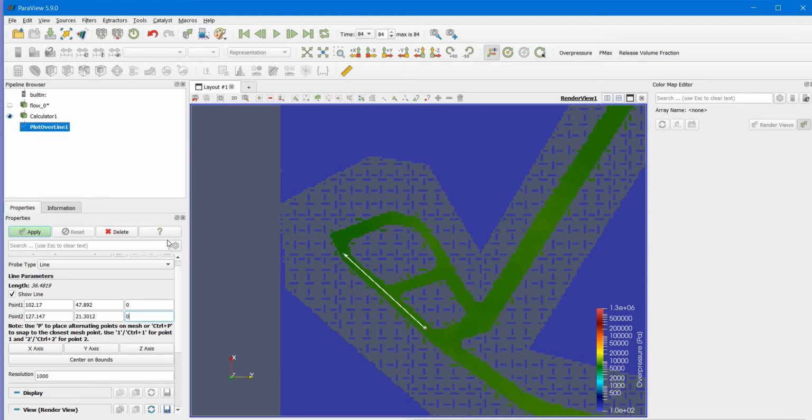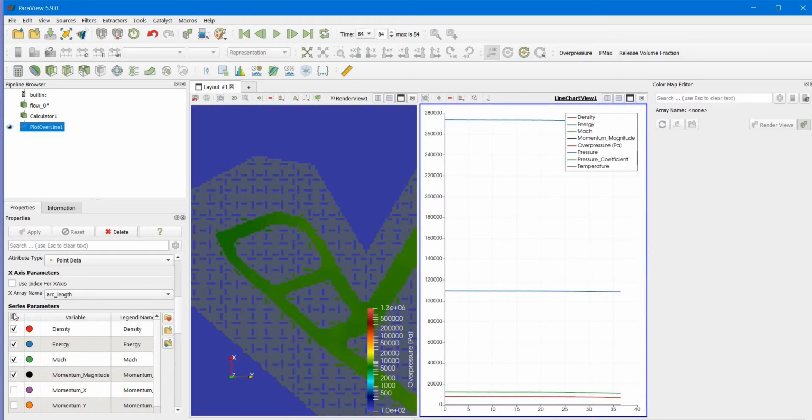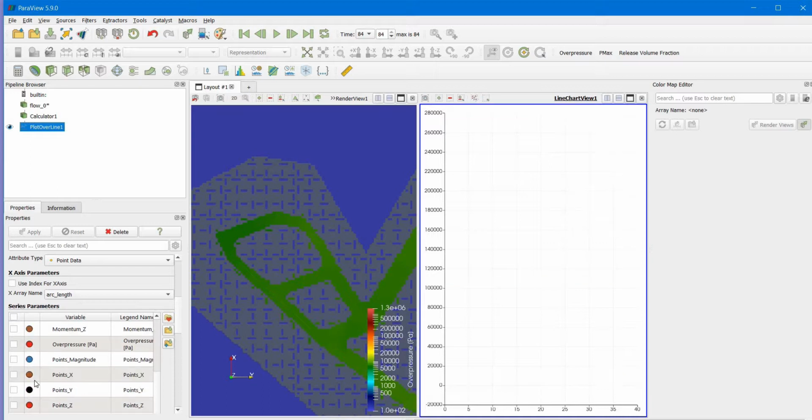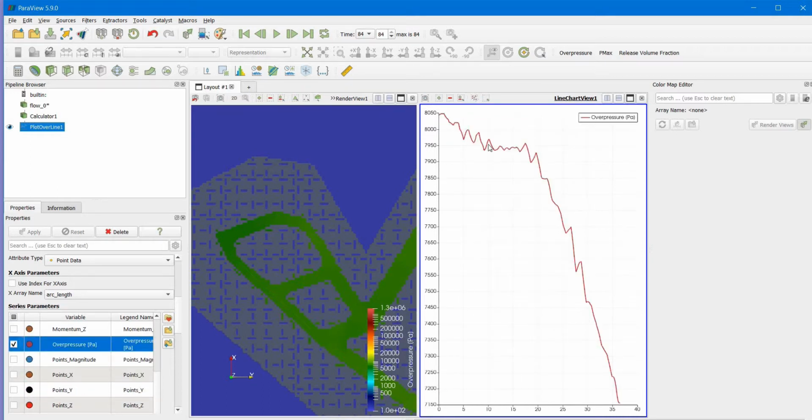And so if I apply, all I'm looking for, I don't care about the other stuff now, is the overpressure. So I've got 8,000 pascals, so that's under 0.1 bar. That in itself won't kill anyone. So unless there's structural damage here, which this maybe can cause, I think people would survive. But let's see if this is the maximum that you get. So we really want to animate it over time.